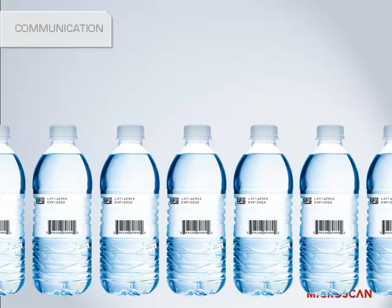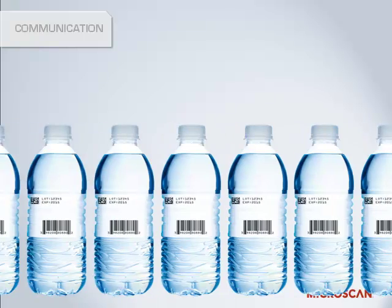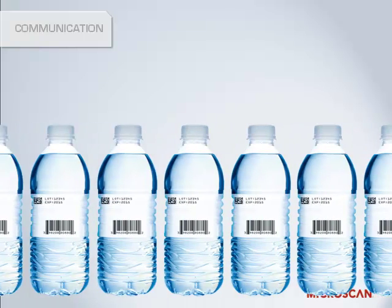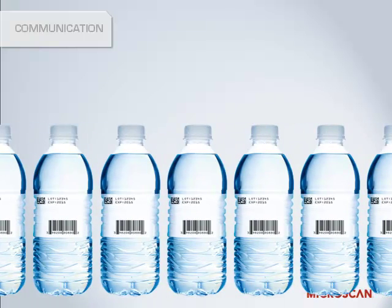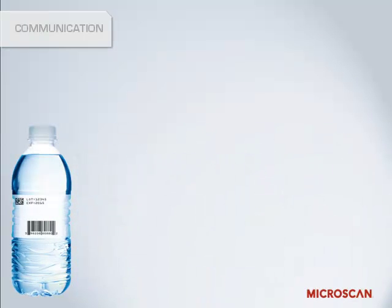Let's look at how these different parts work together to create a machine vision system. In this example, we are inspecting the fill level and cap alignment of water bottles. We'll begin the process by triggering the inspection when the bottle comes by. This will trigger the lighting to illuminate the bottle so that the camera can clearly see the necessary features.